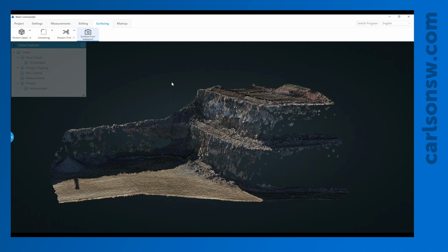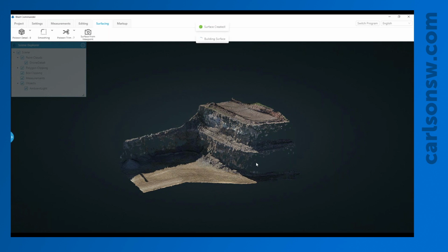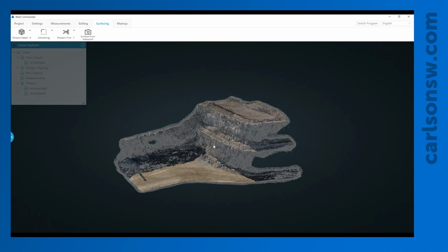And while we can go to surfacing and quickly create a viewpoint from this, we're creating a best guess of what that profile is. Whereas if we were to use a drone in conjunction with the Quarryman, for example, we'd be able to overlay the two different point clouds together to get a complete picture of what that face looks like.